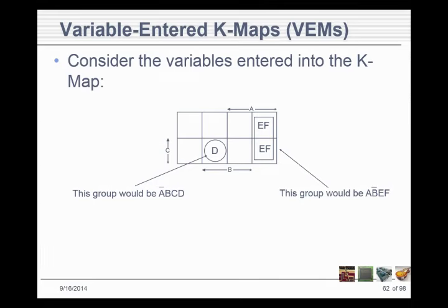What is the point of the variables? Why would we do this? Because how many circuits would you have that are real circuits that are restricted to only 4 variables? You might have 20 variables, and you're trying to simplify something. You don't want to work in multi-dimensional K-maps, so you have to start working in other forms. Actually, once you get up to like 6 or 7 variables, you don't even want to use K-maps anymore. You want to do something completely different.